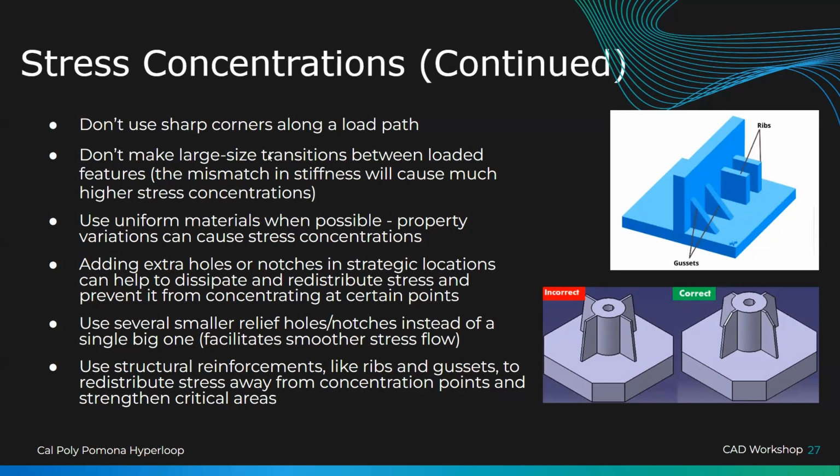I think I went over this. Don't make large size transitions between loaded features. It just means if features are under stress, don't go from a really big one to a really small one. Try and make it more gradual.